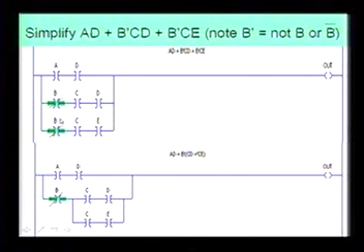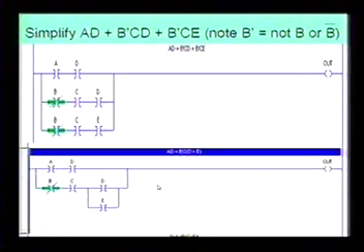So here, we're not going to go all the way through and break it all the way up, but we're going to try and reduce some of the number of inputs. You have 1, 2, 3, 4, 5, 6, 7, 8 inputs to get the output, right? So you have A ANDed with D, ORed with not BCD, ORed with not BCE. Just looking at this problem, you can see that you've got some common instruction, not B. So you immediately just take that out. Just put the not B here, C, D, C, E, and there you can see a reduction as well.